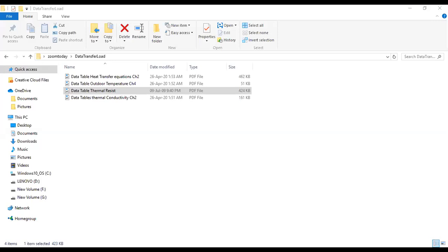So heat transfer also takes place due to delta T, and for that purpose we use U. UA delta T is applicable for glass also. Heat transfer through glass is calculated twice: once for solar radiation, and second for transfer because of delta T, the temperature difference across the glass wall.